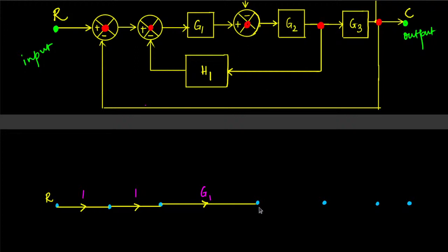Similarly, whatever this signal is at this point goes into this one unaltered, gets another amplification with a factor of G2, and then reaches this node. So if I want to depict that connection, it becomes G2. This connection has a gain of G2, an amplification factor or gain of G2, right? So these weights on the edges in the graph are depicting the amplifications, essentially.